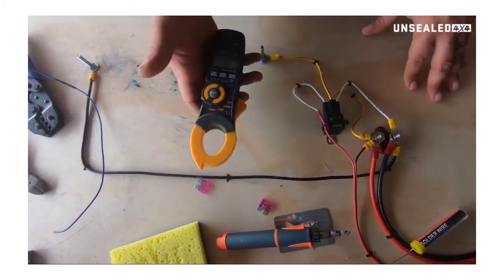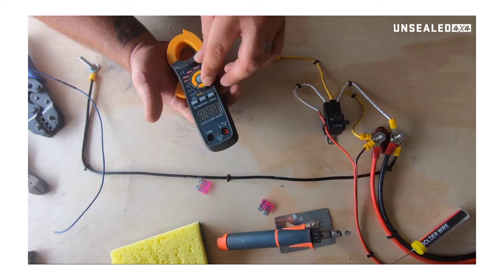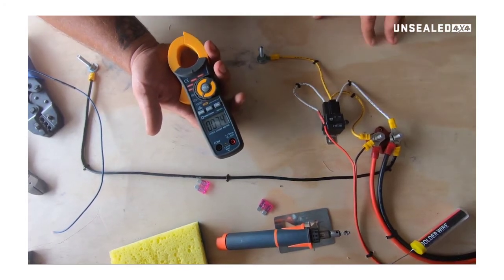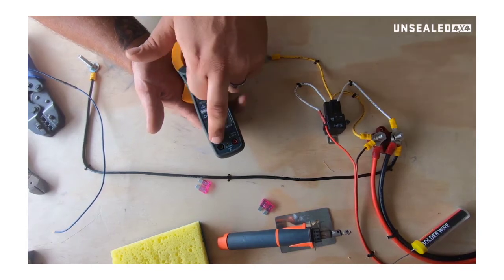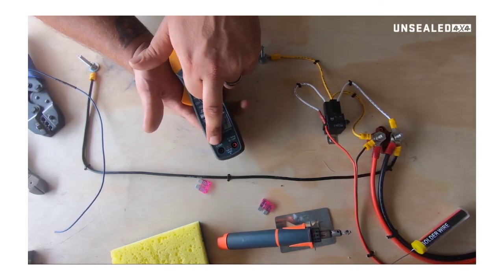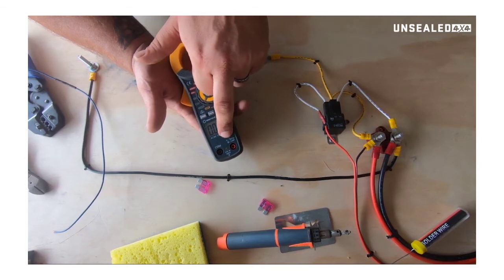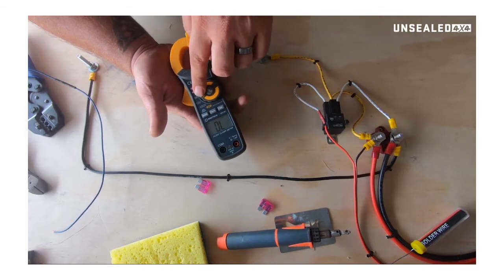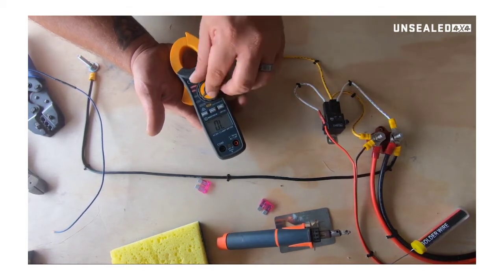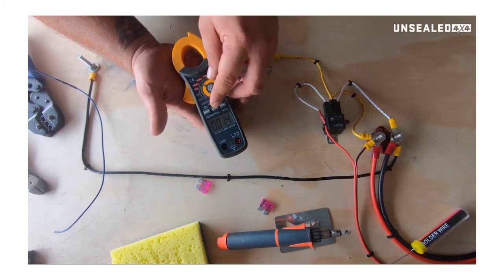What you can also use these little things for, so obviously it will tell us volts. You can use it as a normal multimeter. It will tell us how many volts we've got. Obviously you've got your standard ports. You've got your COM, which is your common, so that's your earth. And you've got your positive, which will give you volts, temperature, ohms, and capacitance. So we can go to ohms with our ports, which are not connected, temperature, and then 40 amps DC, 400 amps DC.